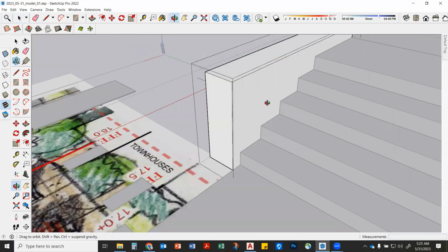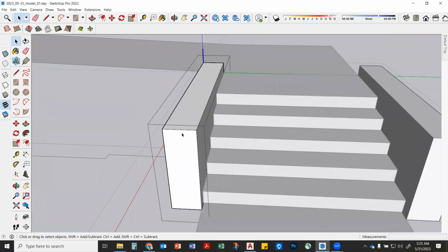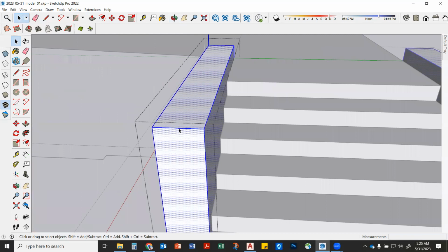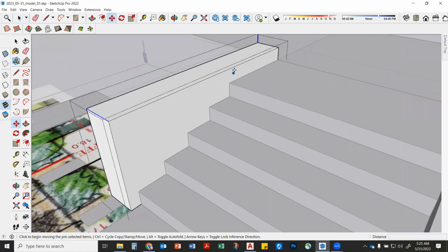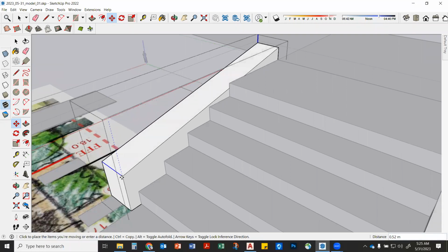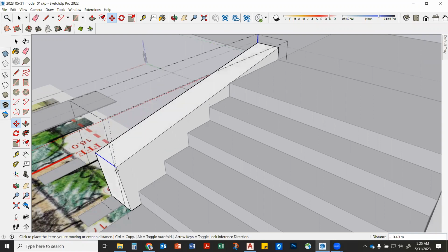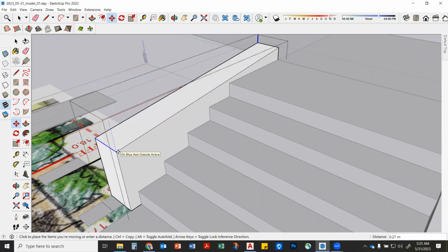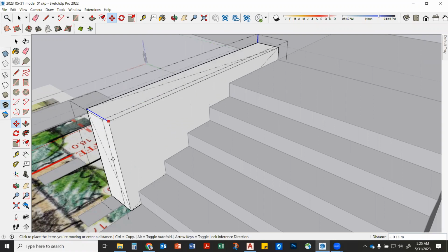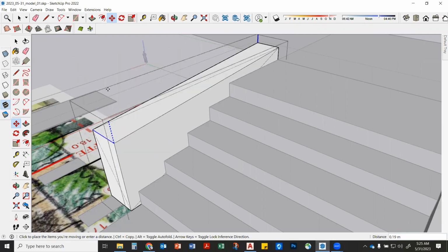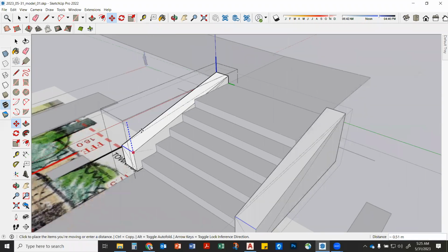So watch. The thing about SketchUp, this is the cool thing. I'm going to make the angle, right? You could just come in and grab that angle, just selecting that blue line up front, right? I could hit move, but I don't have a break line right here. It's going to move this whole face down. So I selected there, and then I'm going to hit M for move. Click here. And then look, if I move down, the whole wall goes down, yeah? If I want it to go straight vertical down, I'm going to hit the up arrow and lock it on the axis. Well, look, they're both doing it. Isn't that great? They're like waving.